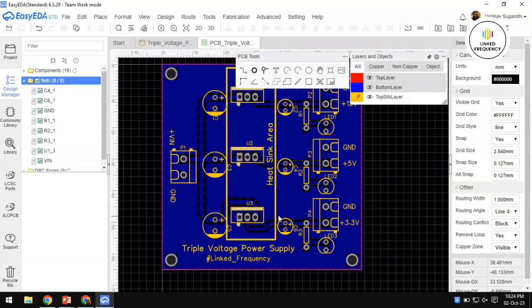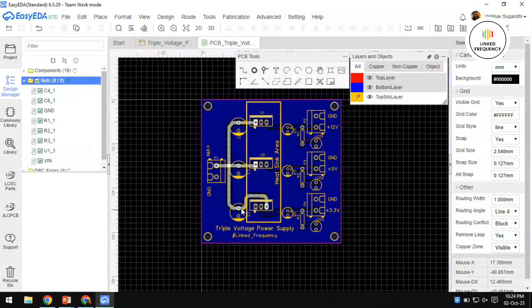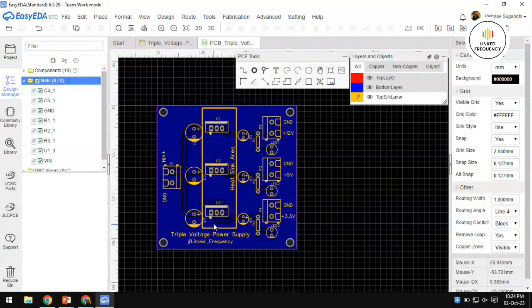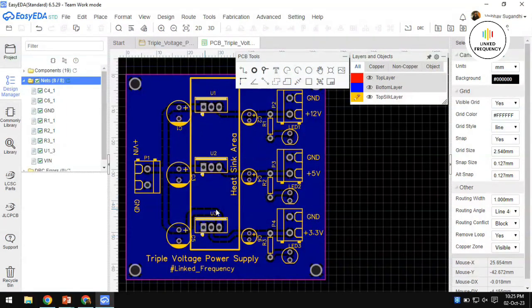and the entire PCB size will be 65 mm by 65 mm, and then we will be having a 3 input bulk capacitor and then 3 regulators. Of course, here you can notice I have not followed the IPC standard that I have spoken about in my previous tutorial. That is all about placing the component, that is heat radiating component, like a regulator on the border edge. I have placed this one at the border edge and these two exactly the symmetry of that particular placement, so that we can add the combined heat sink and we can add a cooling process for that. If you place any component in between these two heating elements, then it is a false IPC standard, or maybe not following a proper IPC standard.